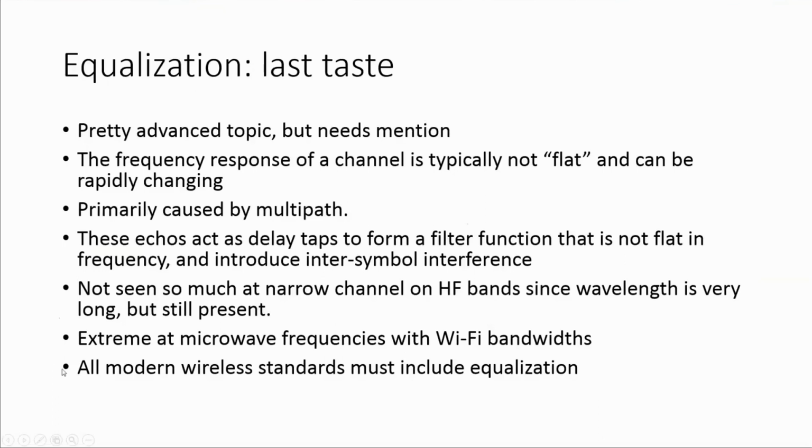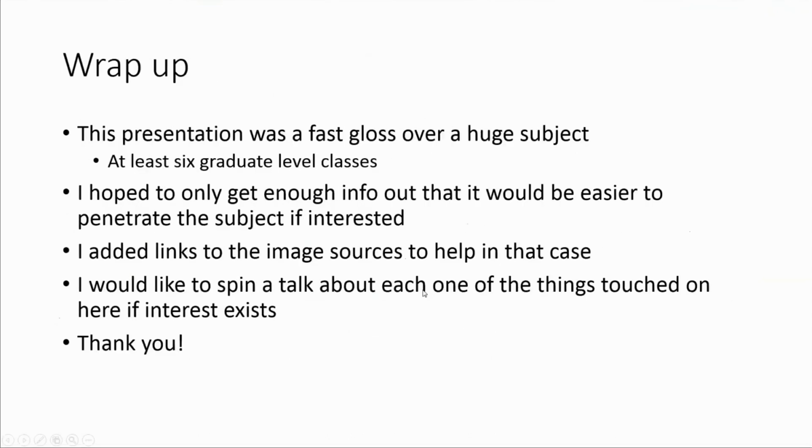Now, the really cool thing about OFDM is that it allows a frequency-dependent fade to be treated as a flat fade. And flat fade means that the frequency response is flat. And they do that by individually weighting the carriers. That is the main reason why OFDM is used. It's an extremely powerful way to fix this problem. And with that is my last little bit of information that I was hoping to communicate. I didn't even write it here, but OFDM makes a flat fade. So there we go.